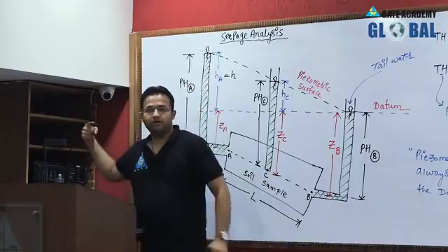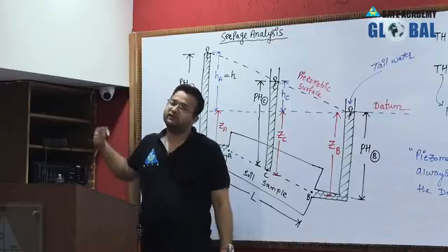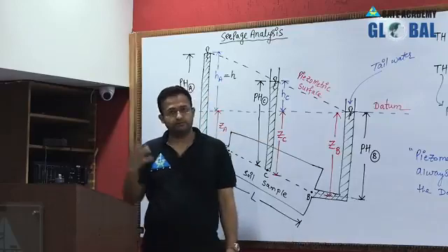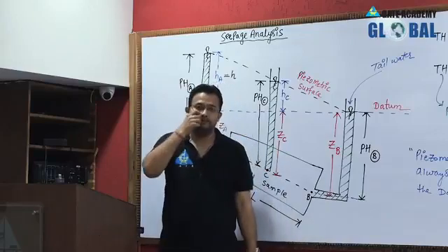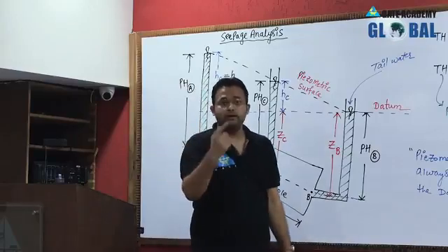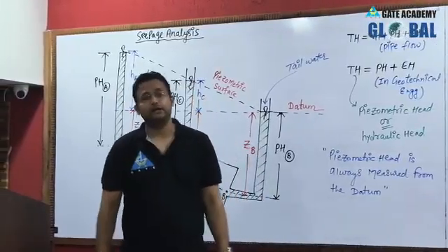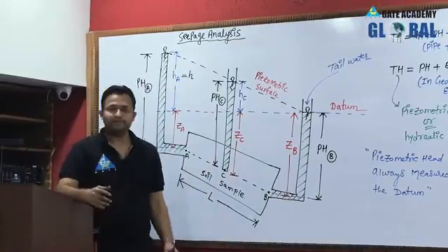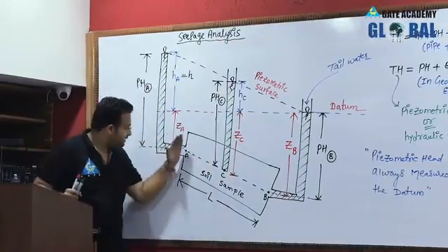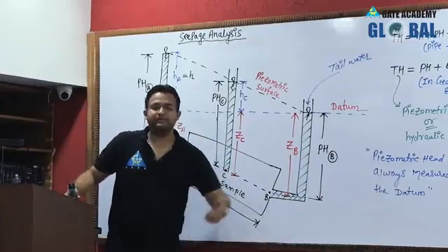If the water is flowing in this direction, then force will be applied in this direction, meaning the water will apply the force or the pressure on the solids in this direction only. So in the direction of flow, pressure occurs, and this seepage pressure depends upon the available head. You people should ask me, sir, is the seepage pressure the same everywhere? I will tell you no. Everywhere the seepage pressure is changing.